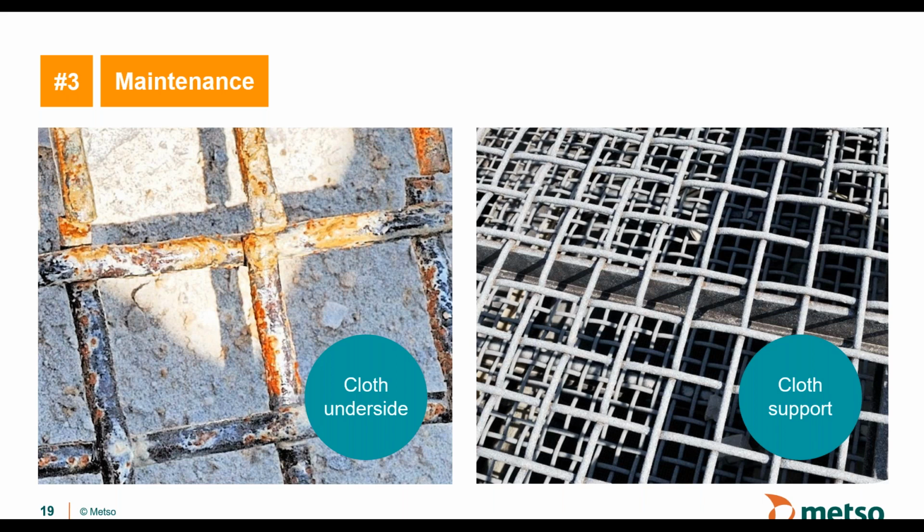And there you can see that the cloth is broken, and you can be 100% sure that the breakage of the cloth in that location exactly matches the location where the stringer is. So it's movement between the cloth and the stringer, and worn stringers and so forth that causes this. So that's the background behind it.